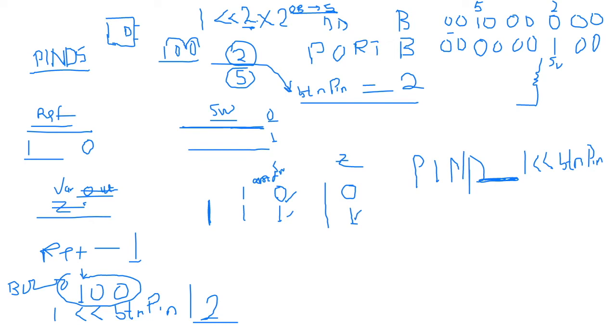So as expected, simply, if I pick my signal, which I want to read, pin D, currently the switch, because remember, this is the whole of pin D, or, yeah, the whole of that port. So the whole status on port D. But let's say I pick pin D, and then I do an AND with a 1 on that particular pin I'm interested in, in this case pin 2, which is the same as button pin.